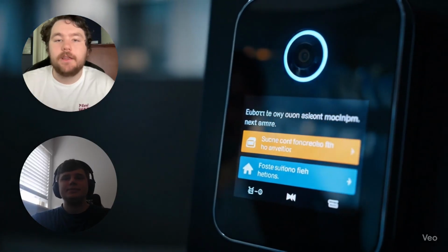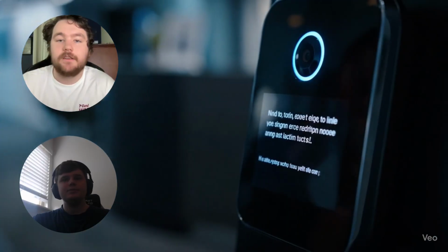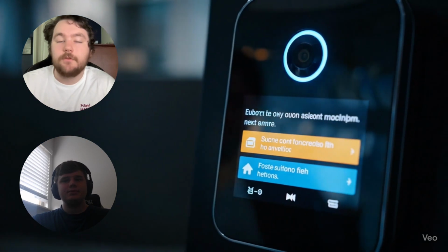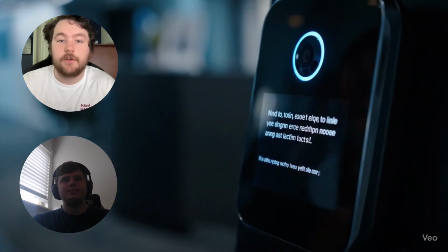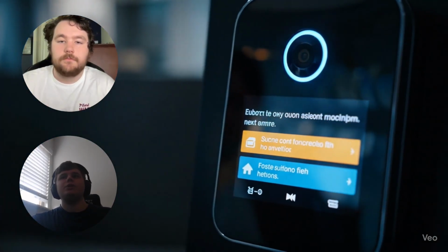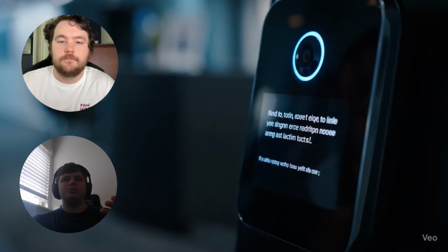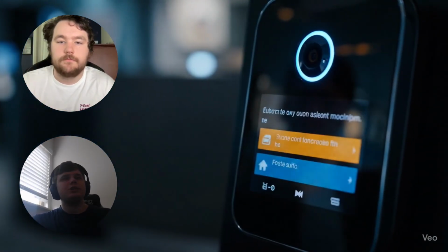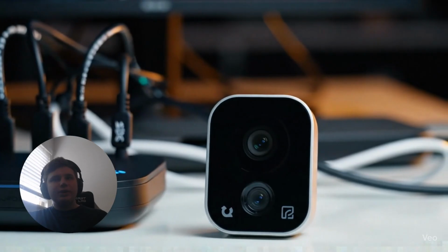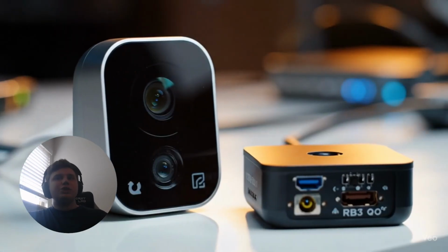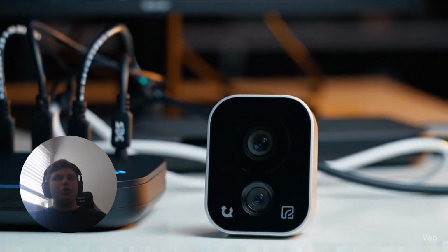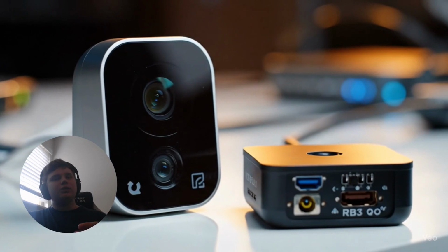The motivation behind OpenGate is that there's a distinct lack of open source projects in the space, and mainly there's two alternatives, which are ZoneMinder and Frigate, but both of these are passive NVR solutions that give you passive security. There are proprietary options like Nest and Ring, but they have their own flaws. Like they share their data with their company, so it's a security flaw, and they also need extra subscription fees for full functionality. With OpenGate, our goals were simple: full open source hardware and firmware, no mandatory cloud subscriptions, easy integrations with home automation platforms, and secure and privacy first design.